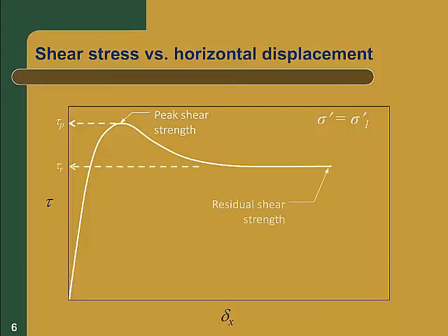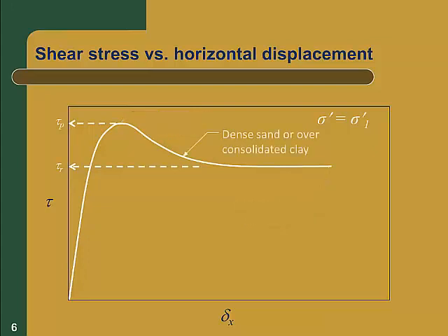The interlocking of soil particles in these soils generates relatively high shear strength. As this strength is exceeded, the particles start to slide and roll over one another. This causes an expansion or dilation of the soil in the shear zone, and the strength of the soil is reduced. The strength loss eventually levels off as the soil reaches a new equilibrium state. The second shape of curve shows a monotonically increasing shear stress as the horizontal displacement increases. It eventually reaches an asymptotic peak strength.